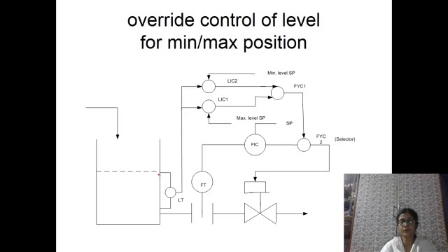If it is for the upper level, it will choose the upper level controller output, and if it is for the lower level, it will choose the lower level controller response. In order to choose the lower or upper level, there is another selector, FYC.